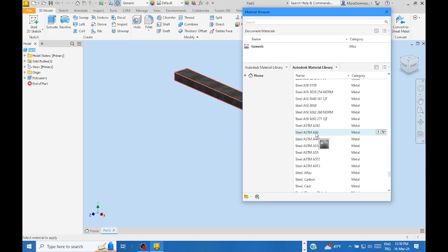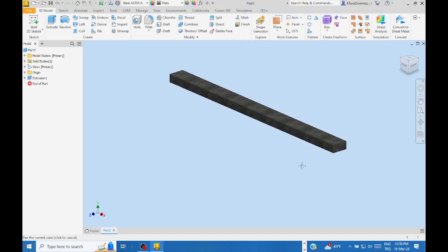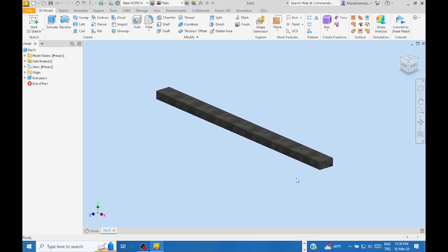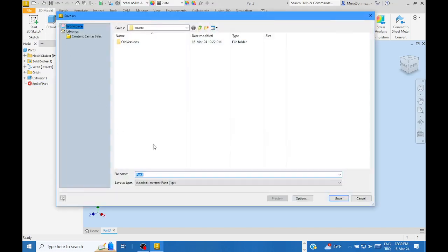With a click indicate this material, and then right click the mouse. That is the procedure in Inventor to input material. Right click the mouse and select in this short window the assign to selection option, and then close the dialog box. Okay, our object is ready to deal with the rest. Save this file in the memory. Which memory? Project folder. Click on Save button or select Save As for the first saving.